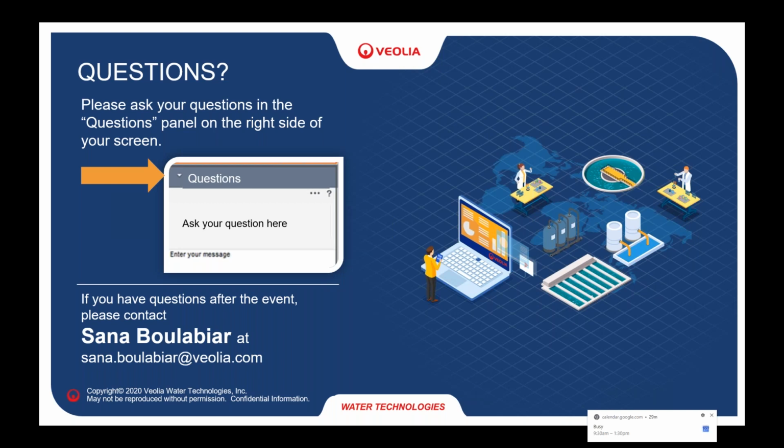One of our potash plants in Canada, K+S, has I believe a 12-meter diameter crystallizer for KCl, a DTB crystallizer. So it can get very, very high. We are not limited by capacity. It's the opposite. Crystallization fits very well into very big capacities. Maybe the confusion comes from the fact that some of the two references I'm showing have moderately low capacity, 50 ton, not very high, but we can really achieve very, very high capacities.